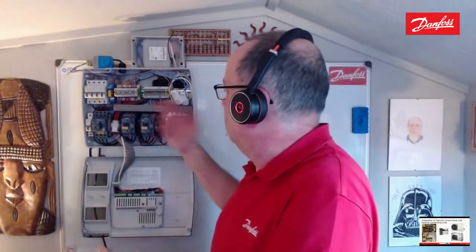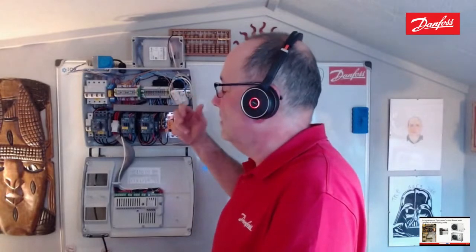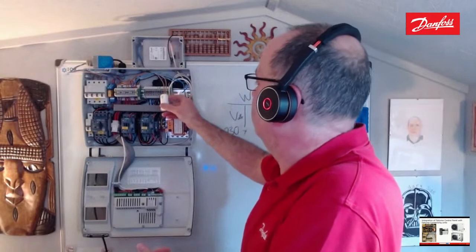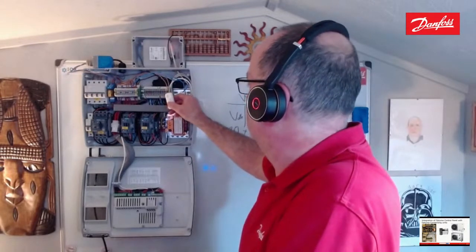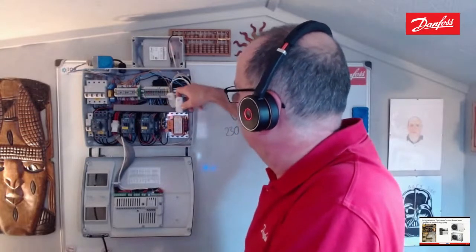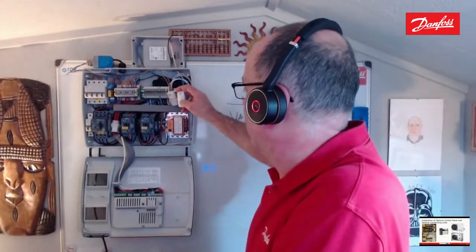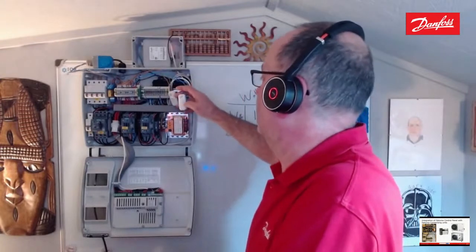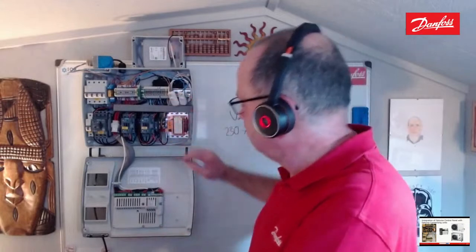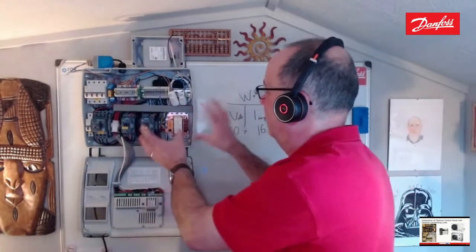This has a safety built into it, so if the door switch is activated for a period of time, then the controller will override it and start the refrigeration system again. But I always quite like a door switch, because it stops a lot of problems. So we'll just put the refrigeration system back on again, and you can see there I've wired in my own little pump down LP, which again does the same thing. It pumps the system down. It's a bit of a hybrid panel, this. But yeah, that's the sort of functionality, I guess, of our control panel.